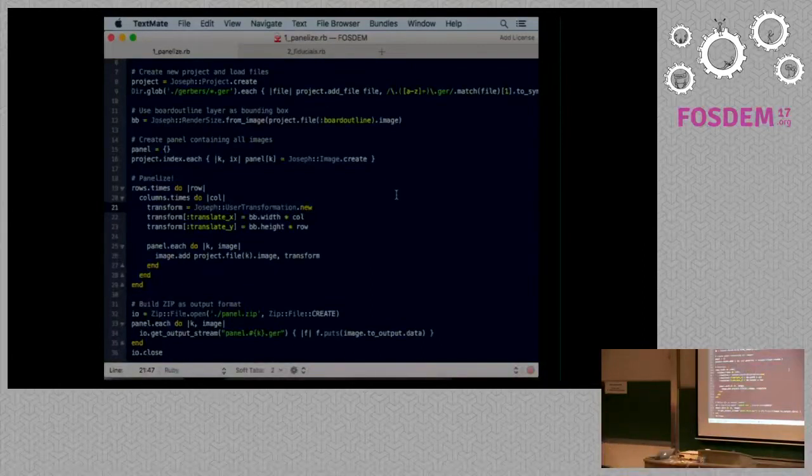What about the information for the pick and place machine? So if you get a panel out of manufacturing, I guess you send the whole panel to assembly, and then how do you get the updated coordinates for all the boards you placed on the panel?